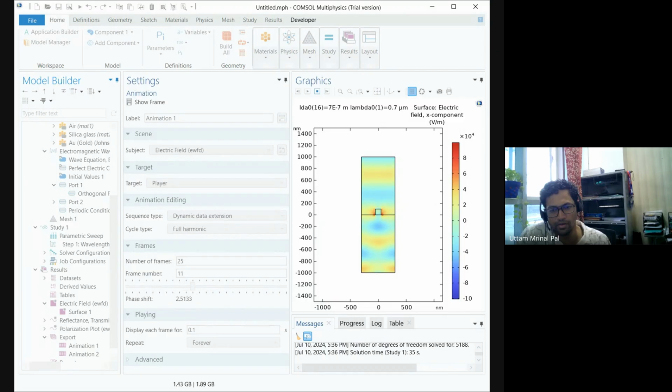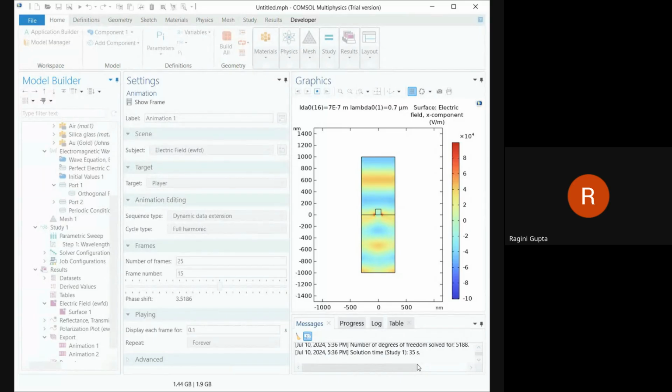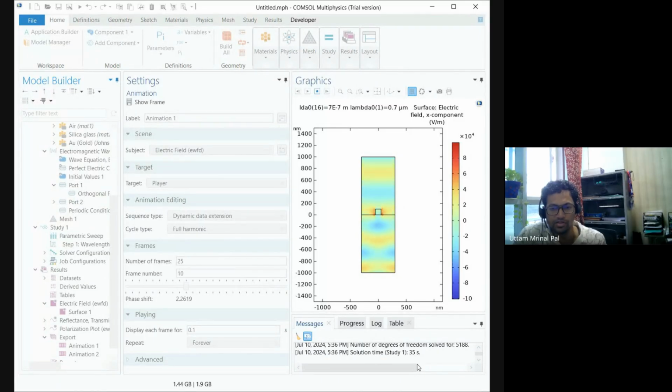One way of interpreting the result is that because of the conductor, you can see there are some reflections as well as energy being propagated. Because the conductor is eventually a PEC domain, the electric field would be zero inside it, so it tries to reflect. So it reflects and the energy is propagating from the sides. Even if you plot the power, you will see that it is actually going sideways.